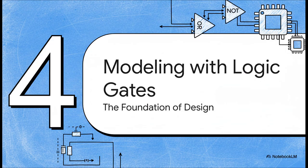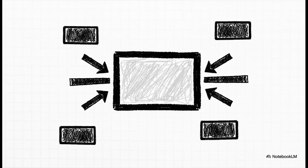Okay, enough with the individual tools. Let's see how they come together to build something real. We're going to dive into what's called gate-level modeling. And honestly, the best way to think about this is like building with digital Legos. Each little brick is a basic logic gate. So pretty much everything in Verilog is built using something called a module. A module is basically a self-contained circuit. It's got its own inputs and outputs. Think of it like a little black box that does one specific job.